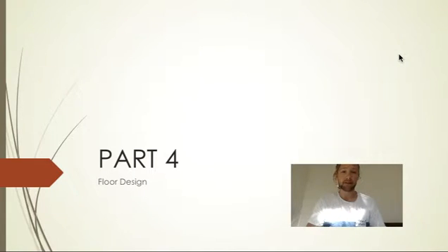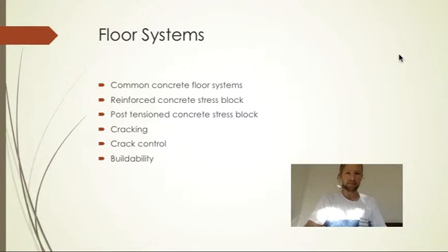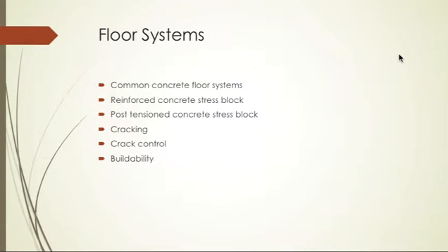Today we're going to be covering floor design. So what we're going to cover today is common floor systems, including one-way slabs, two-way slabs, waffle slabs and so forth. We're going to go back over the reinforced concrete stress block. It's important to understand the theory behind the slab design, also the PT, post-tension concrete stress block, cracking, so the different forms of cracking, and why your slab will crack.